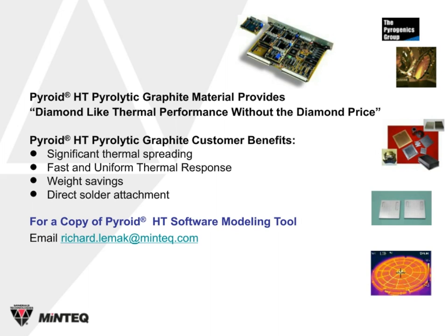One of the follow-ons to the case study that I showed you for the laser diode was a case study where we are able, through machining and orientation of the material, to create a near isotropic system. Of course, when you do that, you have to sacrifice a bit of the average thermal conductivity, but you still can yield an average thermal conductivity of 1300 watts per meter K for the near isotropic case. So, good question, and the answer is yes.